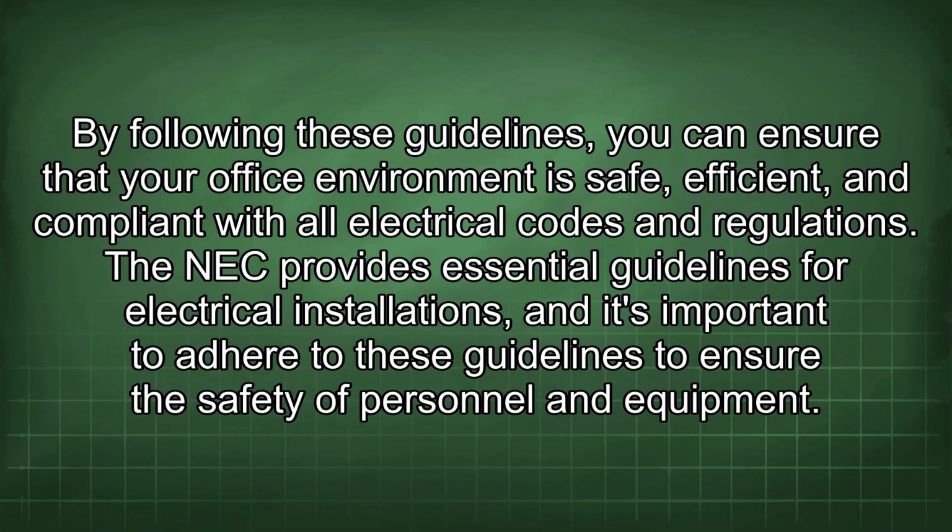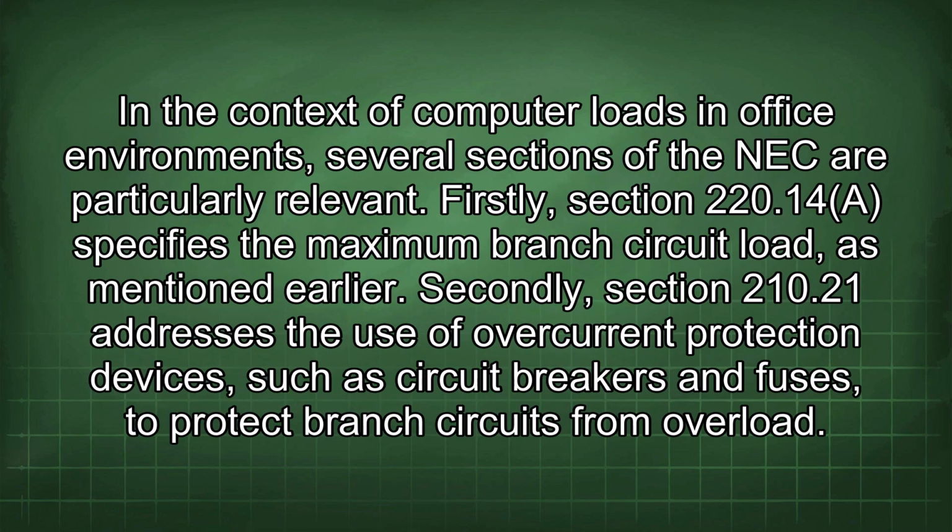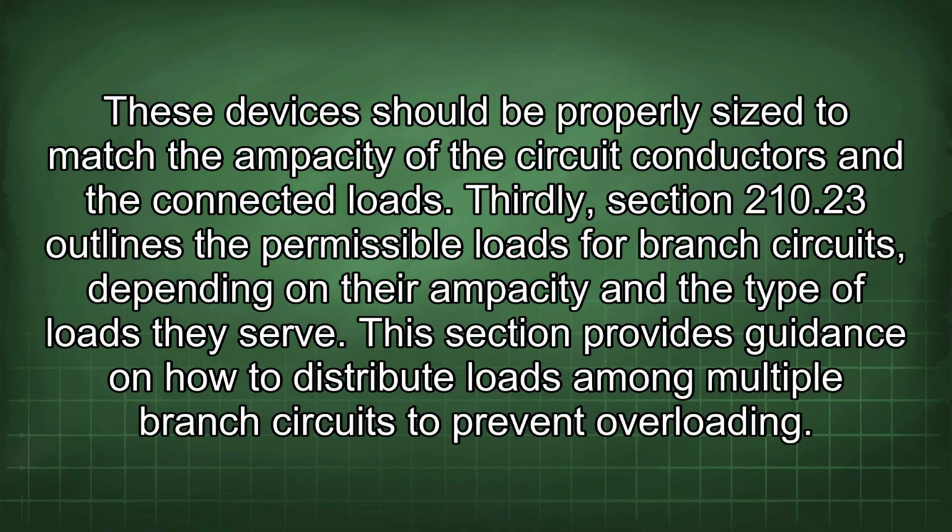The NEC provides essential guidelines for electrical installations, and it's important to adhere to these guidelines to ensure the safety of personnel and equipment. In the context of computer loads in office environments, several sections of the NEC are particularly relevant. Firstly, Section 220.14 specifies the maximum branch circuit load, as mentioned earlier. Secondly, Section 210.21 addresses the use of overcurrent protection devices, such as circuit breakers and fuses, to protect branch circuits from overload. These devices should be properly sized to match the ampacity of the circuit conductors and the connected loads.